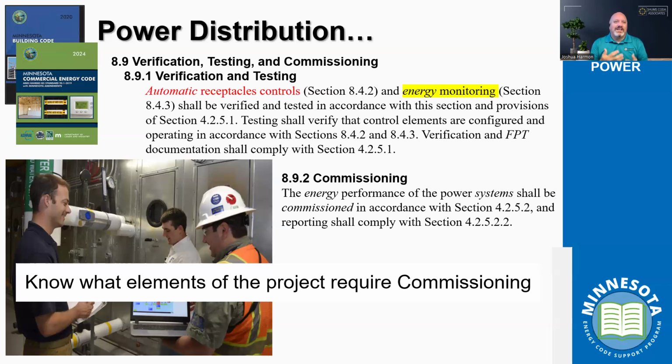They're still running. The fan is still running. All these controls, all these components are running. And so they're really just all giving out at the same time. You installed them all together and you just lost 20 of them at once. It wasn't electrical. It was a control issue. And so again, that's where the monitoring system can help and say, look, you're constantly running power. You only use this area of your building once every week. Why do you have constant energy consumption? Again, digression, but that's the why behind the requirement for energy monitoring, functional testing, and commissioning.